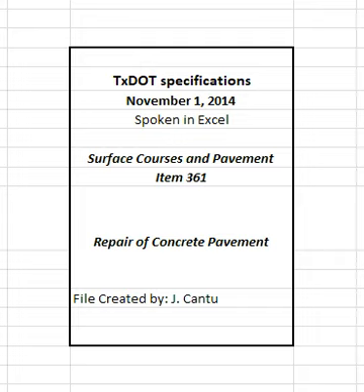3. Equipment. Provide tools and equipment necessary for proper execution of the work that meet the pertinent requirements of the following. Item 360, concrete pavement. Concrete demolition equipment. Provide chipping hammers or hydro-demolition equipment for the bulk removal of concrete. Concrete lift-out equipment. Provide steel chains, lift pins, and a crane or front-end loader capable of lifting the concrete and loading it onto a flatbed or dump truck.